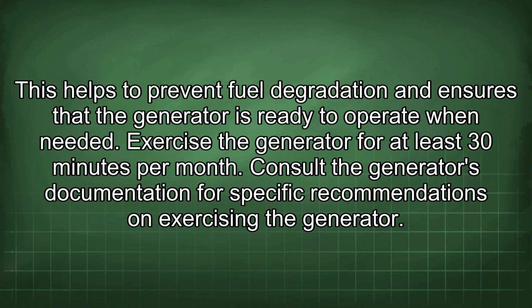This helps to prevent fuel degradation and ensures that the generator is ready to operate when needed. Exercise the generator for at least 30 minutes per month. Consult the generator's documentation for specific recommendations on exercising the generator.